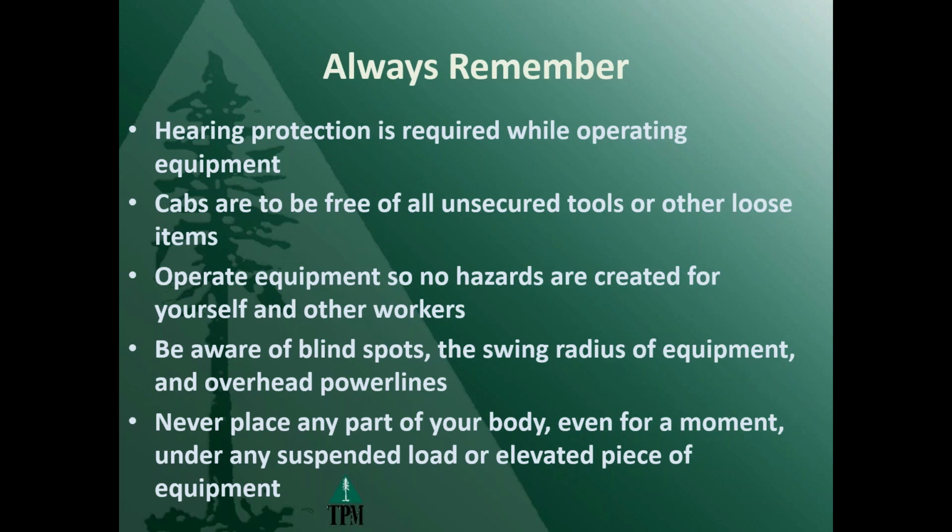And we can't be putting any part of our body underneath a load suspended or a piece of equipment or an attachment up in the air. We cannot be putting any part of our body, even for a second, underneath that. And we did have a fatality last year where basically a piece of equipment came down on somebody. So it's happening, but we've really got to drive this point home, not just for our operators, but for our folks on the ground too.